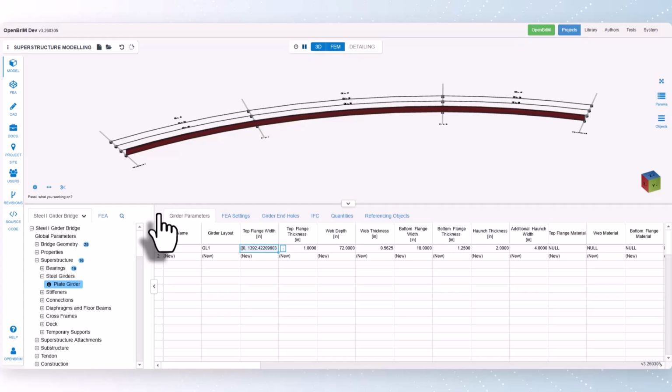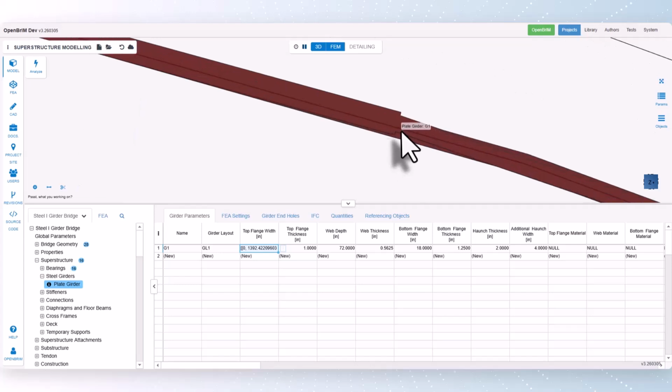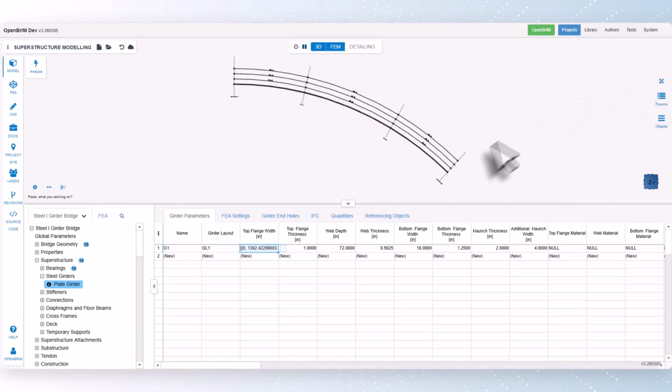After the girder is created, we click the +Z direction for plan view in the direction indicator at the bottom right and examine the dimension change in 3D view. It is also possible to modify dimensions collectively, enabling us to set the measurements efficiently. First, in the data spreadsheet, select the top flange thickness and web depth dimensions. Next, click the three-dot icon button and choose Edit.